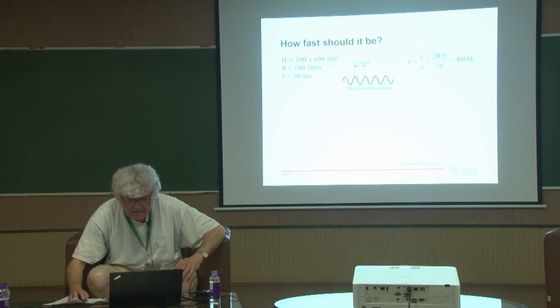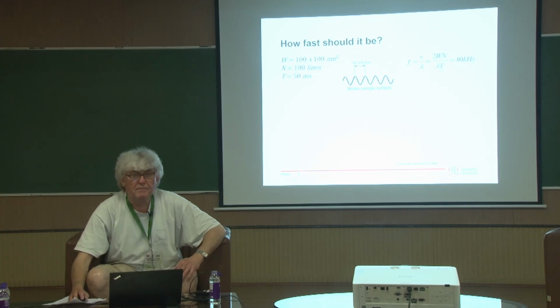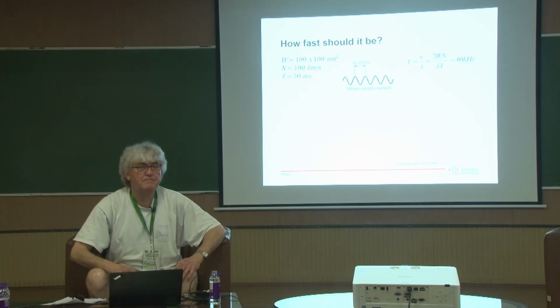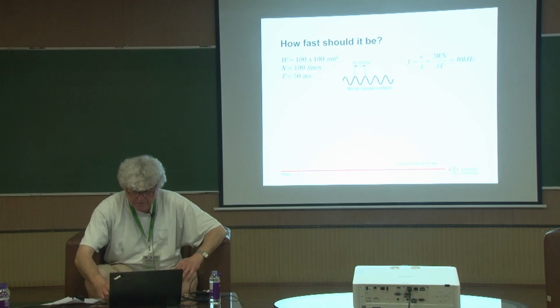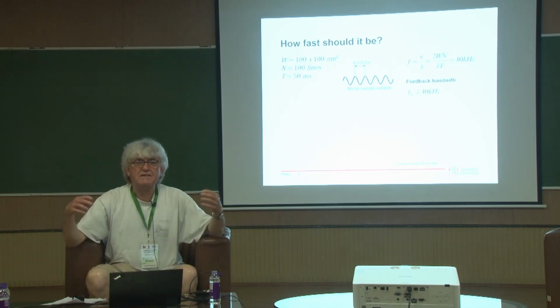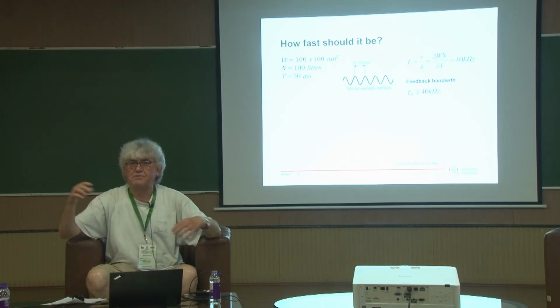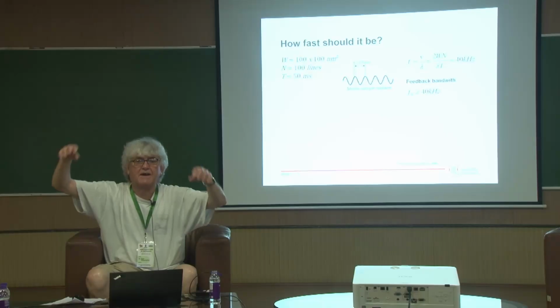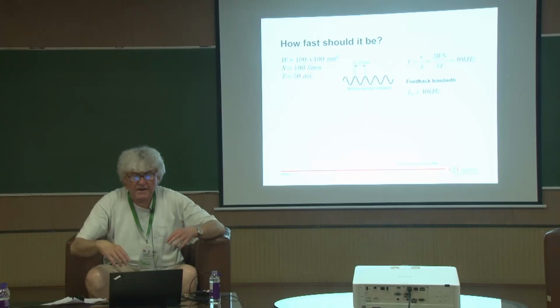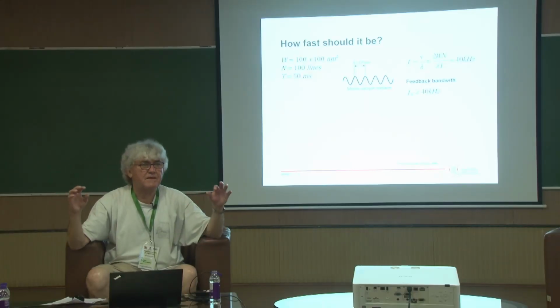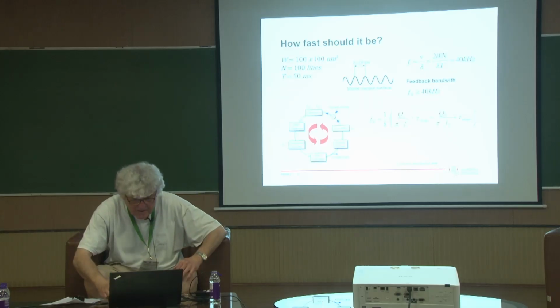So this is all the time you need. With the wavelength of 10 nanometers and the time of 50 milliseconds, we reach a frequency of 40 kilohertz. So this is the image frequency. What you need is a bandwidth that is higher than 40 kilohertz, of all your detection and electronic system, to be able to image with this time resolution.